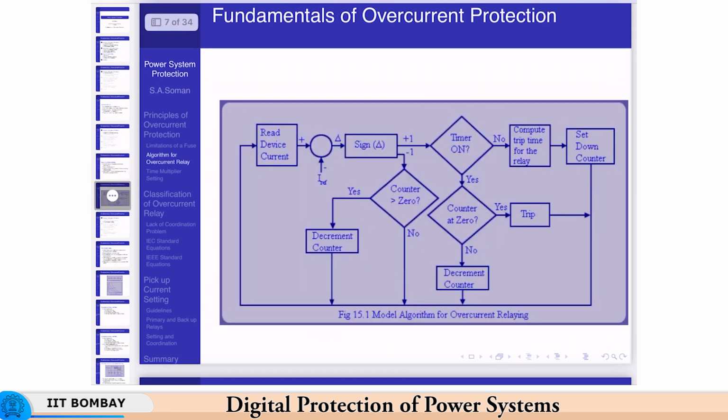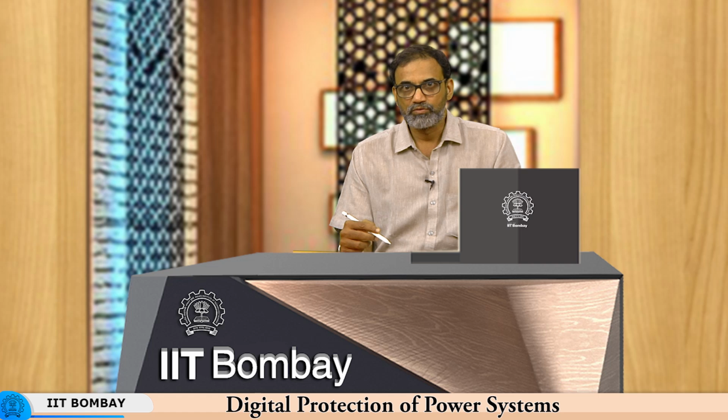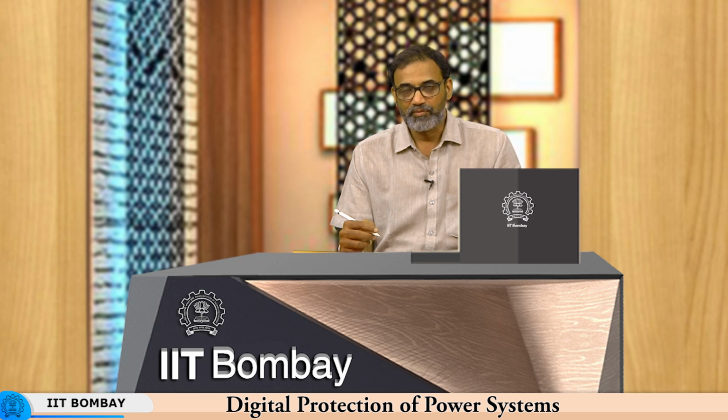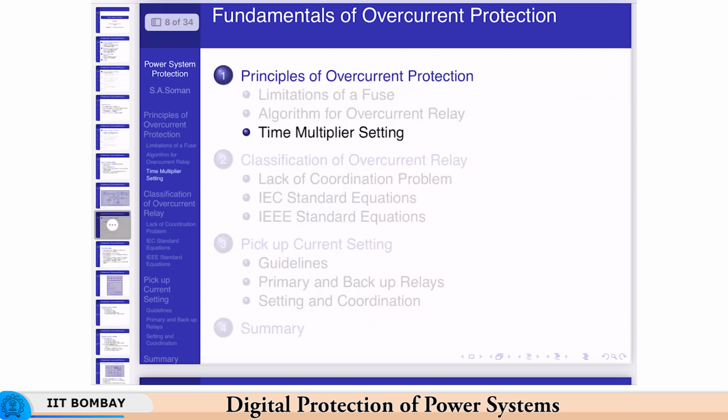This is how the algorithm will look like. There are two counters. One is for introducing a weight so that no transients cause a tripping of the relay. The second one is a timer which is included if the relay operation itself has to be delayed. This is not an inherent counter, but a timer which is given to the user so that it can increase the time setting of the relay so that it can perform a backup function as well. What is a primary and backup function? We will have a look at it in greater detail in the coming few slides. So, we will move on.